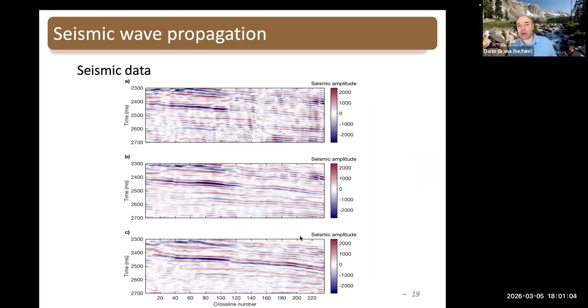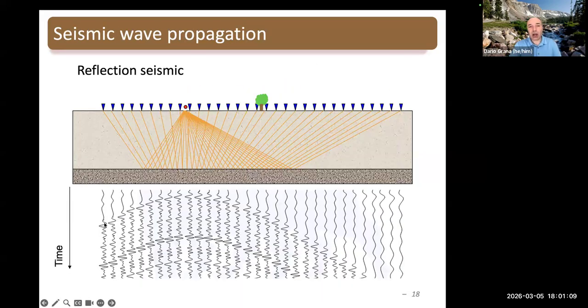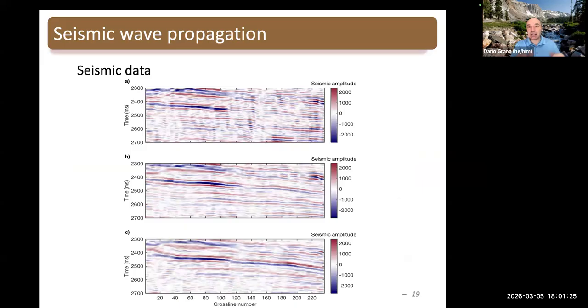So here's an example of how the seismic data looks. Essentially what I did is just take, oops, sorry about that. I just took all these seismic signals for this location here, and I put them together in a coherent signal, and then I moved the source, and I kept doing this procedure, say every 25 meters in the horizontal direction. And now what I get is a bunch of seismograms. I'm going to just interpolate them. So every time you have a peak, you're going to see, for example, a blue color, well, in this case, it would be a minimum. And then when you have a peak, it's going to be a red color.